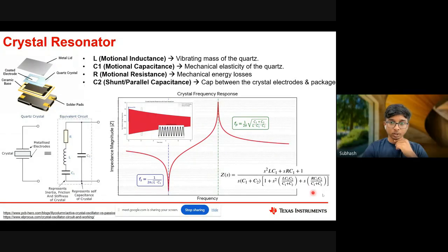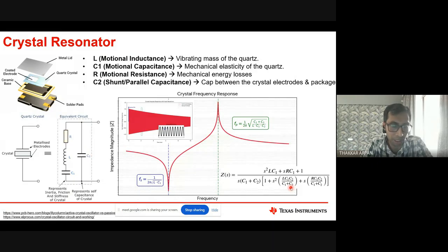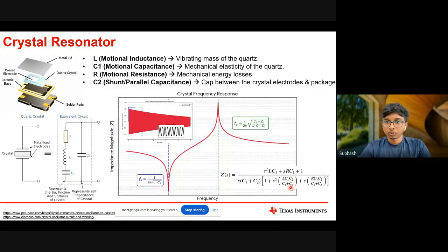Yes sir, a quick doubt. So basically, in most crystal oscillators, you're saying both these frequencies will be very near to each other. But there will be some error, right? Yes, there we want that error. On that only it works. Oh, won't that error lead to phase noise?